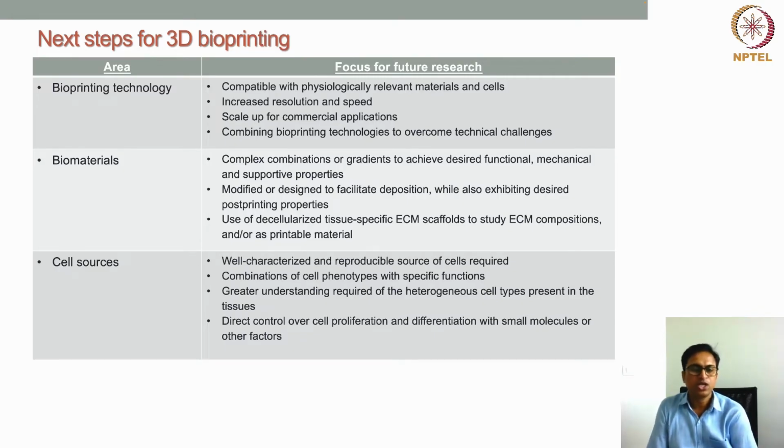If you keep the nozzle diameter at 50 micron, the resolution will probably be better, but it can decrease cell viability, because the cells will be under tremendous shear stress passing through that narrow gap. So that is what we have to think about, how to improve the resolution. For laser assisted bioprinting, that is not the case; there we can work on better resolution.